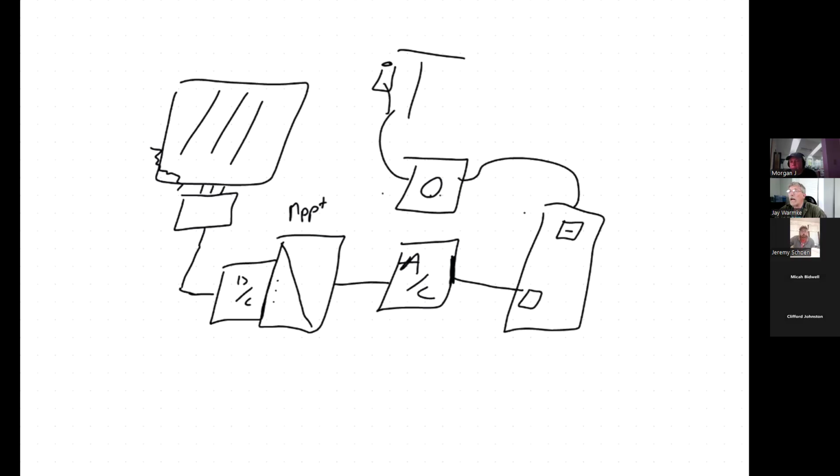Okay. Now, what I just told you, let's say that the house is on fire, they come and they pull this meter. Well, immediately your system is disconnected from the grid. So your inverter should come equipped with anti-islanding, which basically means it's going to shut off as soon as it loses sight of the grid. Oh, okay. It should do that anyway. But then just to be sure, because the NEC doesn't trust automated things really, they say, okay, let's put a disconnect switch there just in case. Smart. Yeah. So you turn it off. Well, now for sure that inverter is shut off.